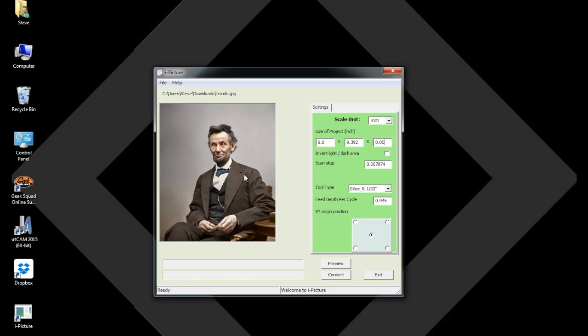And so what we don't want to do is create this really strange perspective. For example, his hair being machined very deep into his head. For example, if I set the maximum machining depth here at 1/2 inch, it would machine essentially a hole in his head where the hair is, and it wouldn't look very appropriate at all. So what I do is I set the depth at 50 thousandths of an inch.